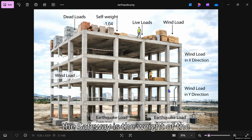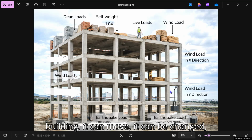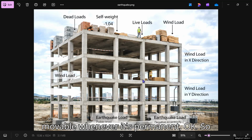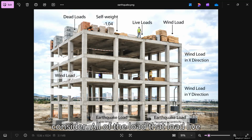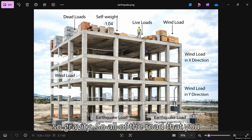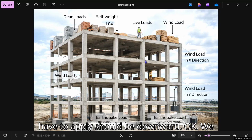So dead load is the weight of the building. It cannot be moved or changed. It's permanent. So this is the first one that we have to consider. All of the loads, dead loads and live loads, will be applied downward. Downward means gravity. So all of the load that you apply should be downward.